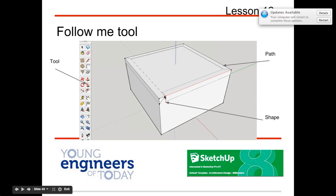So what you do is you create a shape, and then once you have the shape that you want cut out of your object, you select the tool, you select the face of the shape, and then you really slowly, patiently, and carefully trace your mouse. You're not pressing the mouse down, you're just tracing it, almost as if it was a magnet, over your path.